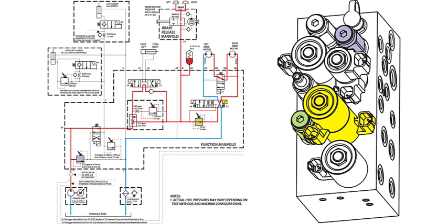The spring-applied brakes are in parallel with the drive motors. As the drive system pressure increases, exceeding approximately 400 pounds per inch squared, the brakes release, allowing the drive motors to propel the machine. When the machine is driven downhill, the drive pressure is reduced significantly. This may cause the brakes to shudder. A nitrogen-charged accumulator is plumbed in parallel with the brakes, storing oil under pressure to prevent this from happening during a pressure drop condition.